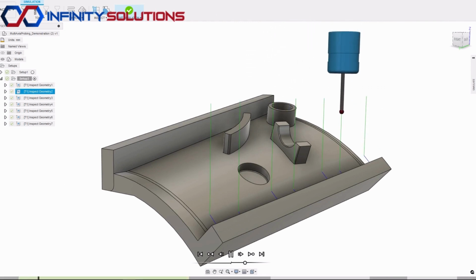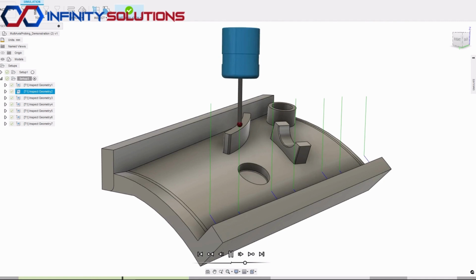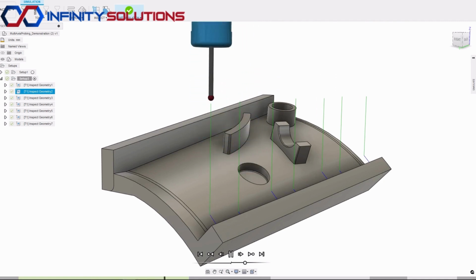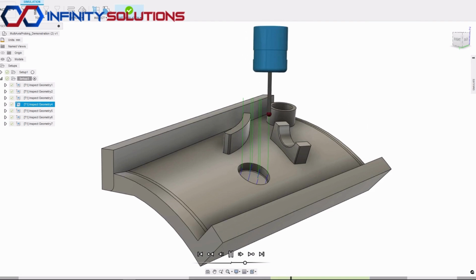The planar and circular fitting functionality uses the probing moves from inspect surface functionality to inspect planes and circles in different orientations. This allows you to probe angled faces, holes, and bosses, which you would not be able to inspect with probing cycles. You can also use asymmetric or unilateral tolerances, which you could not achieve with probing cycles, and apply a tool orientation to the probe feature.